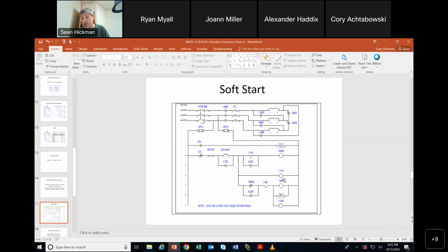It works, but sometimes you get into a little bit of a race. We talked about it earlier with the garage door opening, when we did converting ladder logic, that when this SR comes on, this is closing and these are closing. What's another one? Oh, the motor starter here, motor open. Oh, my time relay. So I got my time relay here. These are opening and this is closing. So you got multiple sets of contacts on the same relay, some opening and some closing at the same time, that you want to be sure that you don't get any trouble with here.